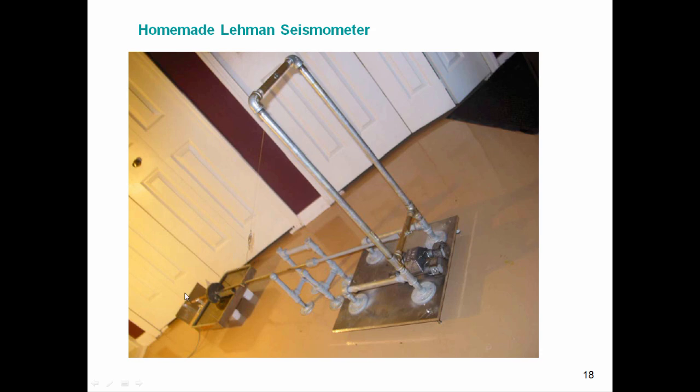But anyways, it operates like a horizontal swinging gate. So this is a horizontal pendulum boom. And the idea is that the pendulum boom remains stationary in its own inertial space while the ground below is shaking. And then there's a sensor that measures the relative displacement from the sensor itself to a little metallic target that's on the boom. I'll show you some additional slides. This will become much more clear. But just a few highlights here.